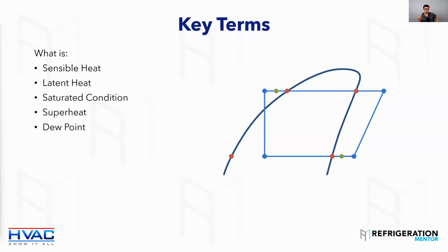Remember that. The dew point for superheat. And this confused me for years, and it still confuses a lot of people. You use the dew point to measure superheat. So with high glide refrigerant, when you're going to measure that superheat, you make sure you use the dew point. And here's where it is. Remember we talked about superheat over here, and this is your dew point line right here. So this here is all vapor. So the dew point is vapor.